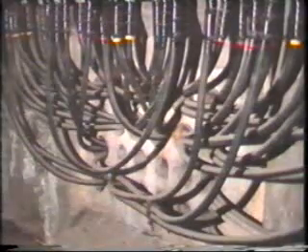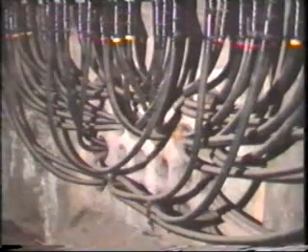This condition is more likely to occur where voltages are 12 kV and higher, and also where the line capacitance is high, for example with long lines or where cables are used. When you think of all of the variables in the circuits, this subject of ferroresonance is obviously highly complex, but it is essential that we understand the principle, because we shall be meeting this term in future tapes when we discuss specific installations.